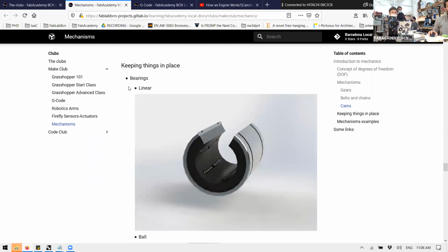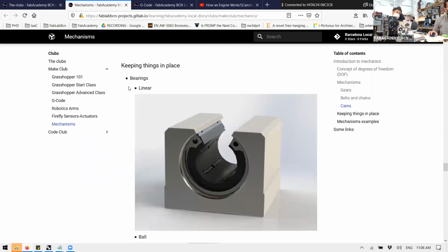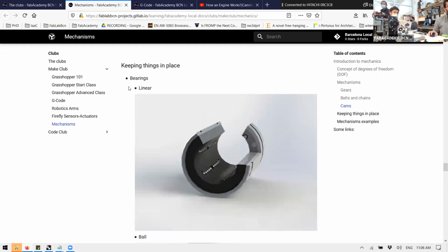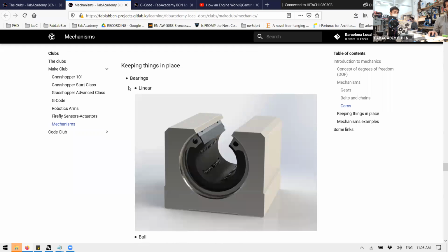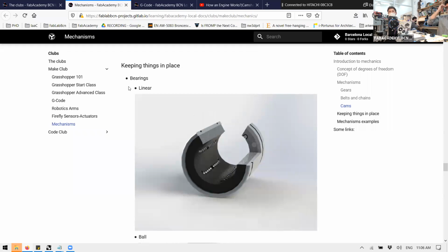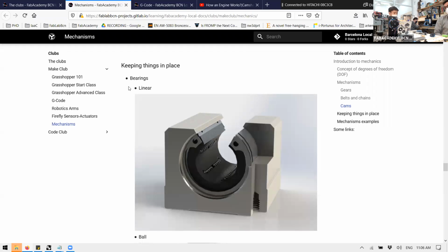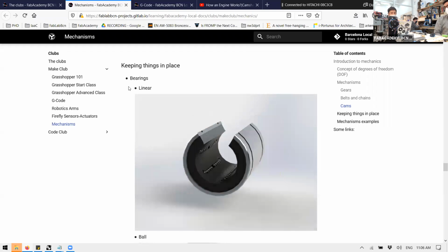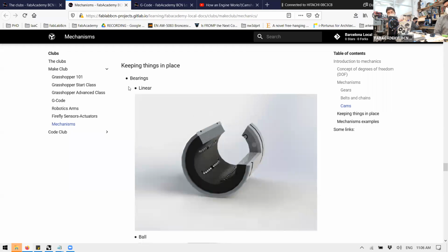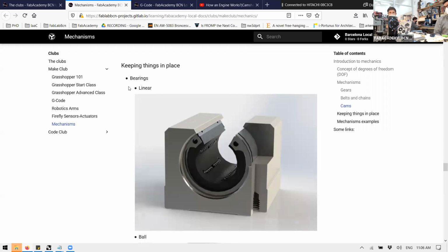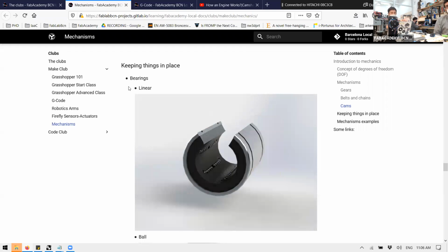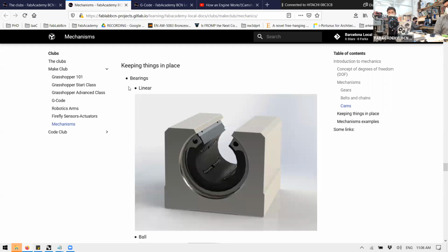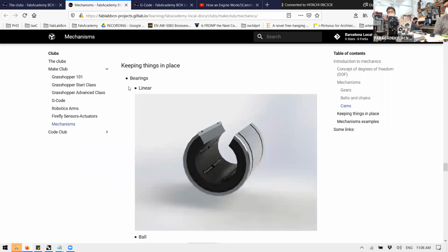And if I understood correctly, this question is, for example, you have this sliding one, two pieces of plastic. There's a way to calculate how powerful the motor has to be in order to move that. You could calculate that, but in general, it's a theoretical calculation. You need to know exactly what the surface finish is, if there's any sort of lubricant, what play you have in here, and that is not going to be an easy thing to calculate. So you normally do experimentation.